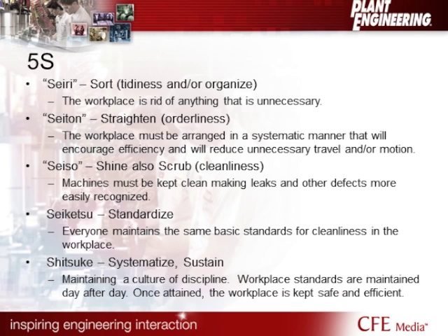So let's talk a little bit about 5S. 5S is broken out into 5 S words, originally from the Japanese, but we have converted them over here in the U.S., and I'm going to show you each of those over the next few seconds. So the first one is seiri, and that is sort, and this has to do with tidiness or organizing the workplace. In other words, getting rid of those things that are unnecessary.